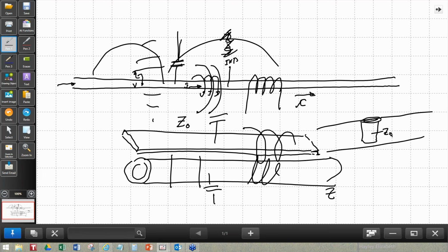Note that when you're thinking about vias, you need to understand that there is a magnetic field. Generally, if current is flowing through a via, there is a magnetic field being generated by it. There is also an electric field being generated through capacitance by it. So when you're using vias, you certainly do not want to put a very sensitive via right next to it where these capacitances will couple. The further away, the better. You have to go a distance away to make that happen.